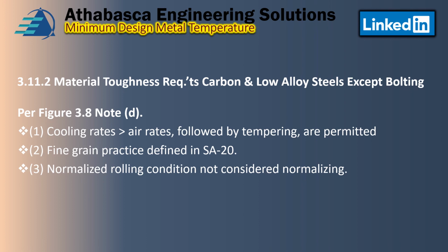Normalized rolling condition is not considered to be normalizing. Once again, very specific. So do not go into Division 2 unless you know you can get the inspection and that your vendors really understand those requirements, because things can get difficult very soon.